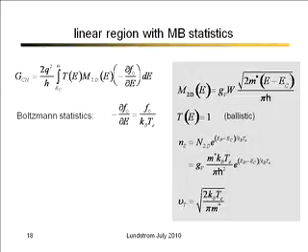One other thing I want to point out is that there are various ways to define thermal velocities. In equilibrium, the electrons are zipping around in random thermal motion. The average velocity is 0 in equilibrium. But if I ask, what's the average velocity of the ones that are just moving in the plus x direction, that are crossing a plane? That average velocity is what I'm calling v sub t here. That's the square root of 2kT over pi m.